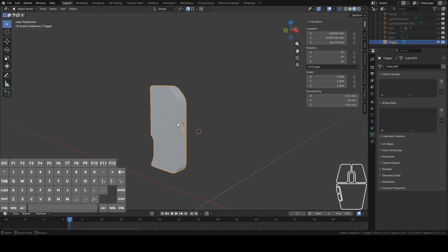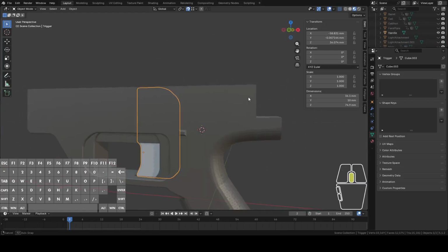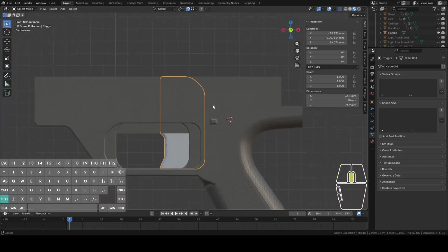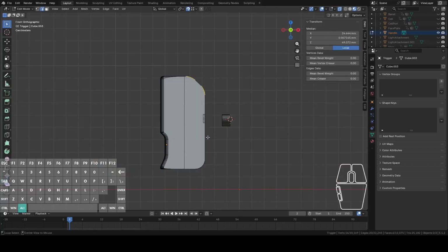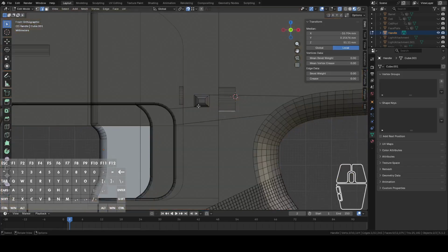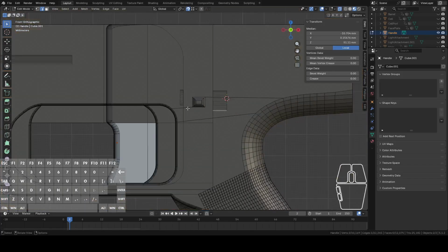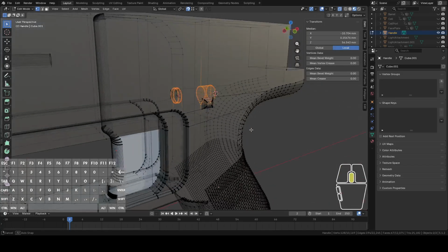And then what we're going to do is move the spring for both the handle and the trigger down. It's okay where it is right now, but it doesn't feel very impactful since the resistance from the spring, let's Alt H to unhide that. Since the resistance from the spring is up here, this kind of moves listlessly a bit, and I'd like to tighten that up so there's a bit more tactile sensation there.